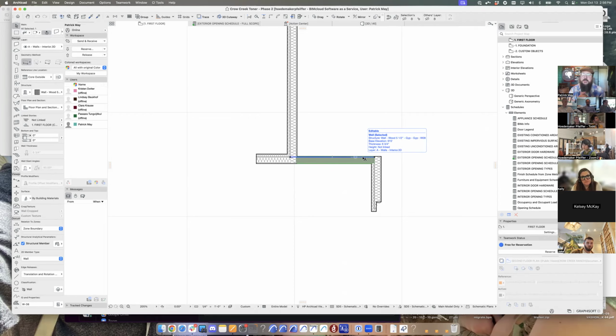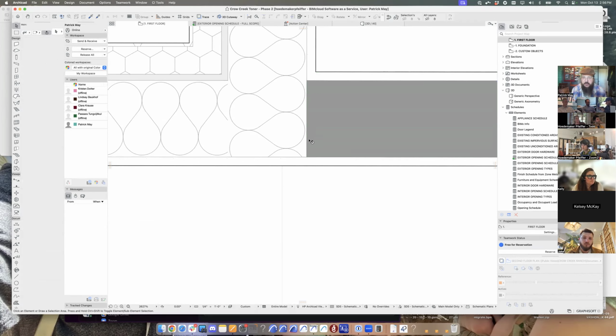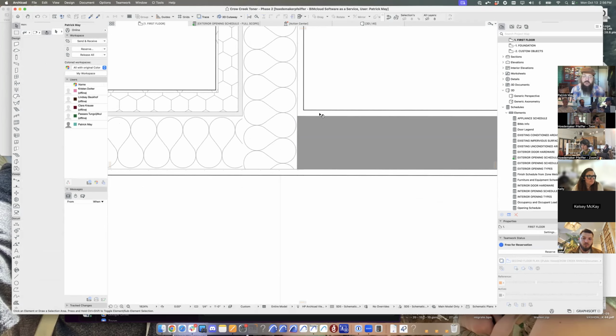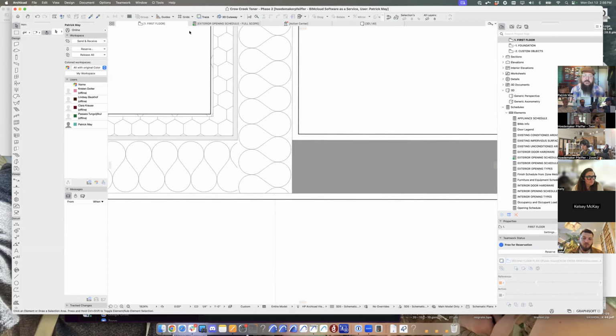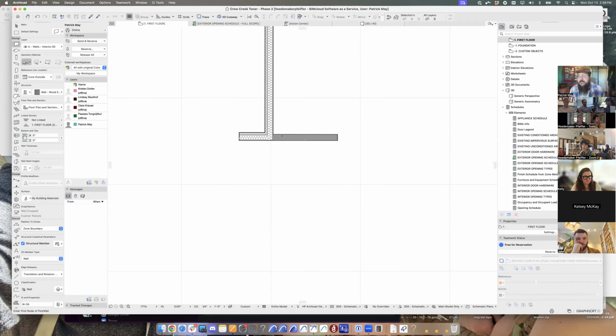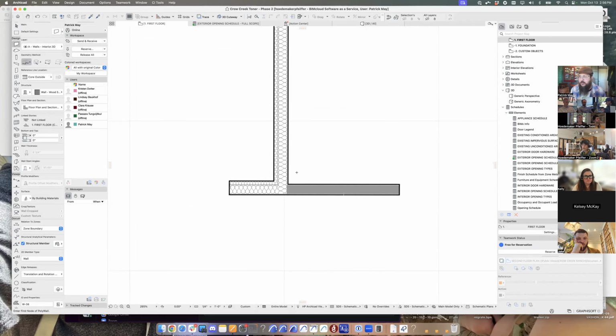It's a bit of work every time I have to do an intersection like that. I account for about half an hour of just troubleshooting, drafting, getting a column in there, cleaning up in plan, section, elevation, 3D. It's a bit more work than is worth. Sometimes we have to look at whether there is an extra line here or there that I don't want to see. We can sometimes clean it up. Sometimes it's not worth that trouble. So you have to take into account how much am I going to see at 1/4 inch? I hate to have sloppy modeling practices. Maybe "as clean as it can get within reason" is sometimes an acceptable way to put it.